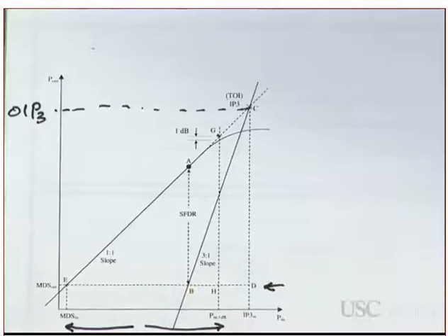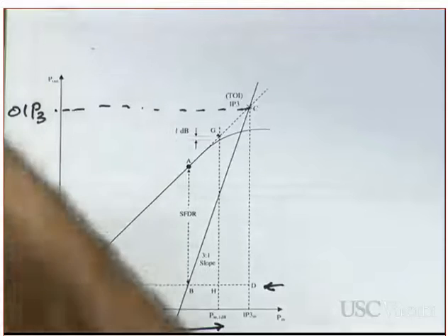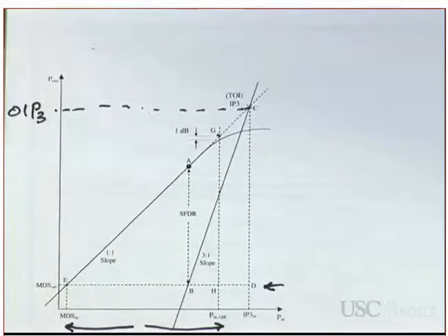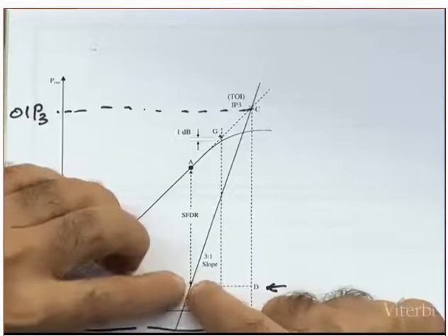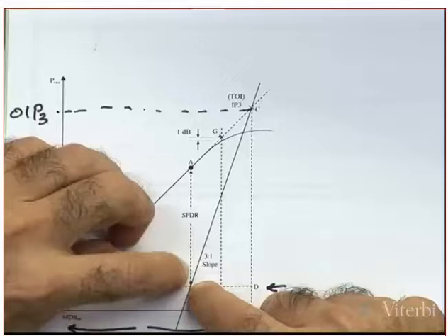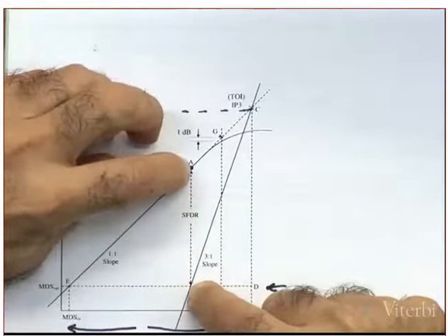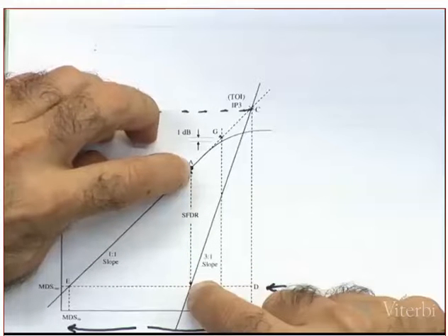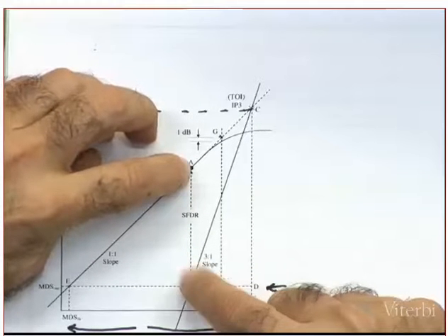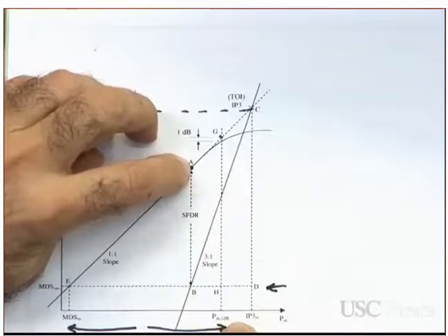That is the point where we can neglect the third order intermodulation, which means we say that the third order intermodulation component looks to us like the background noise. And we can live with the background noise, because there is nothing in the world without background noise. Background noise is always there. So they take from this point all the way to the intersection with the characteristics of the fundamental of the amplifier. Did you understand that or not?